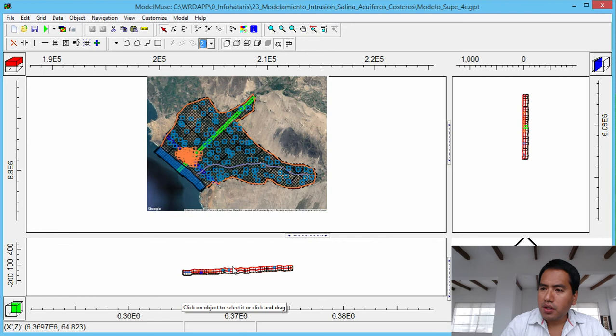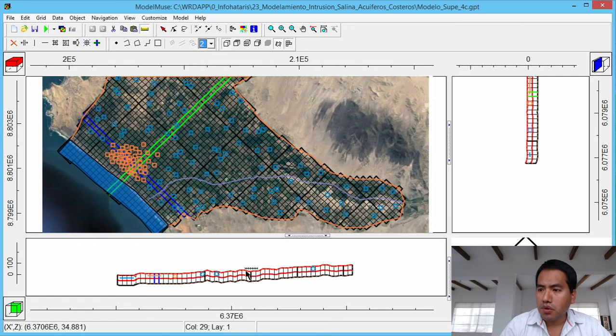The model aquifer is almost 100 meters thick and is divided in 2 layers. MODFLOW-SWI2 can handle the saltwater-freshwater interface within a layer, so in fact there is no need to define many layers if you are working with SWI2. However, if you want to put more focus on vertical heterogeneity or anisotropy, I would recommend using maybe 3 or 4.